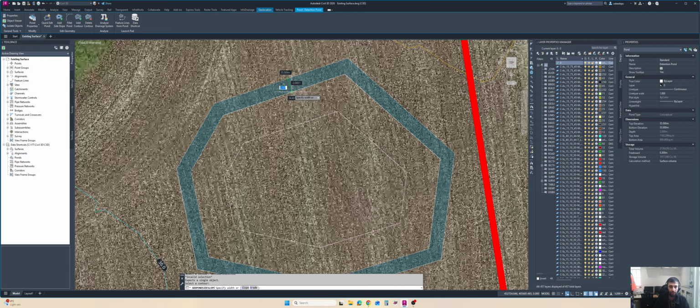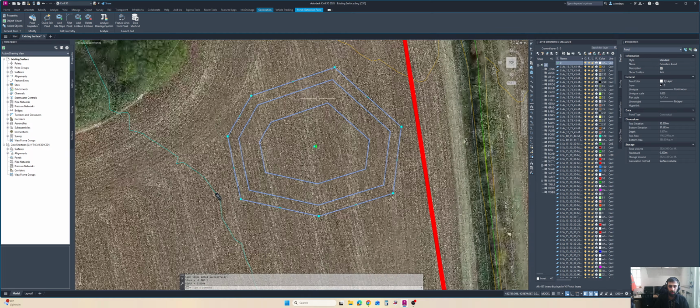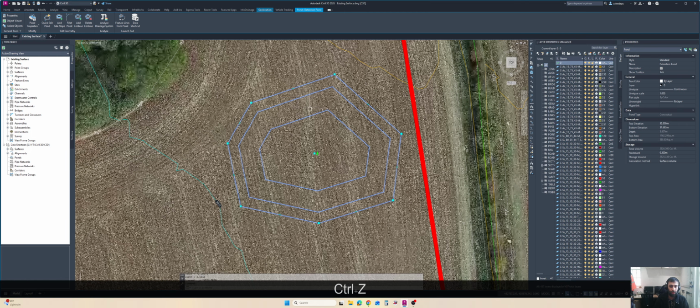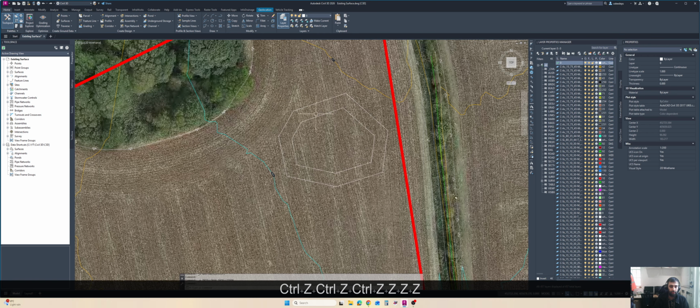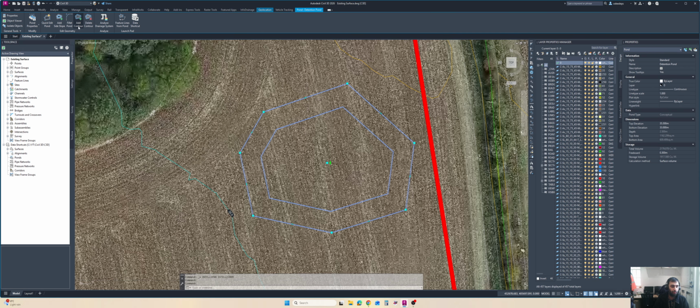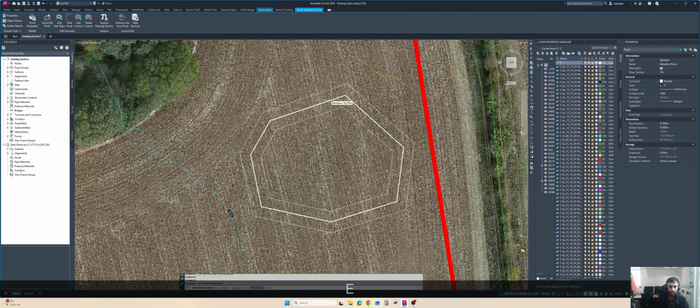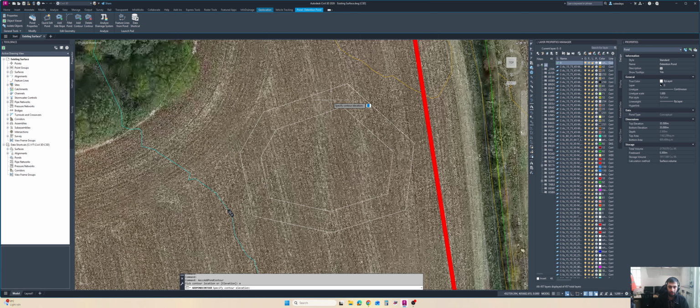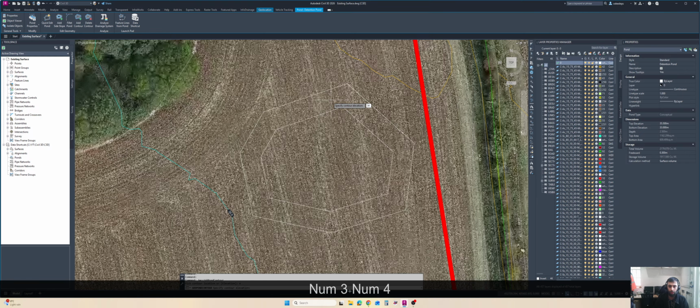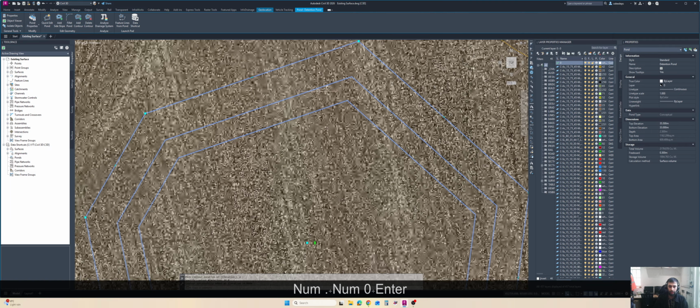So you can see that it has the contours, like for example here, like this one. So it has added another contour, or you can manually add the contour. For example, if I Control Z and then select my pond, add a contour, and you can see the elevation, and I type E for elevation, and it asks you to specify the contour. For example, if I want it in the middle, I can say like 34. It comes like this, the contour.